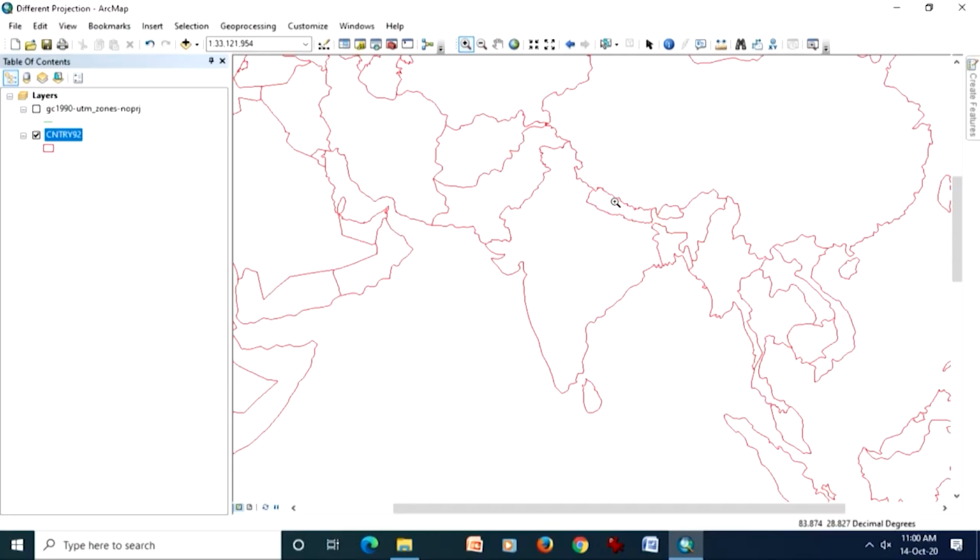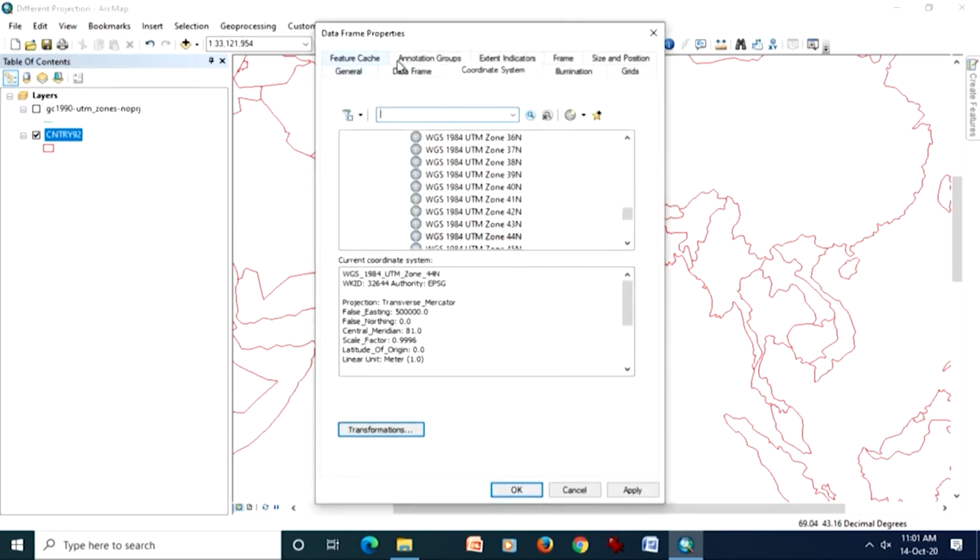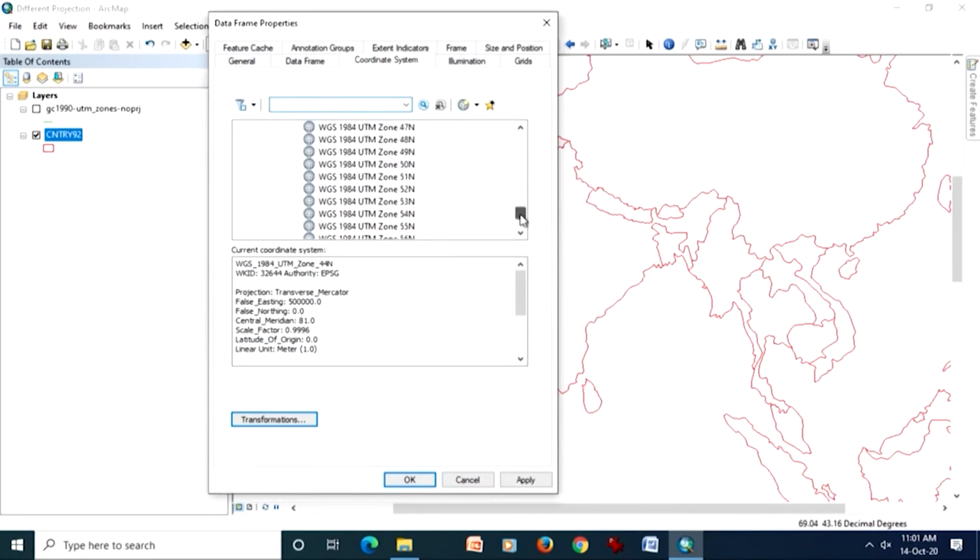That is why I have demonstrated these two things together, because whenever you change from one projection to another, you are going to create no data, and whenever you do georeferencing, no data is created as well. So no data and map projections are in some way linked. The choice of map projections nowadays is enormous, and custom designed projection systems can also be used as per your requirement.